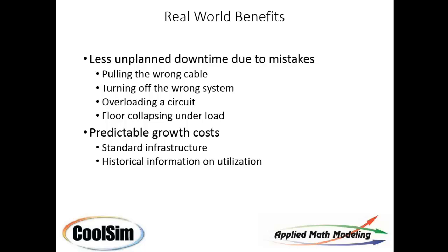As we went to 45U racks and we really started loading those things in with lots of hard drives and got a really heavy load on it, we had a corner of a tile break, basically, and it tilted the cabinet, and we had to get riggers to come in and help move the thing off because we had exceeded what the load was for a tile that was put in back in the 70s. I mean, if you look at the progression over time as to what your loads would be, back then it was pretty common to say, okay, I'm never going to go over 1,000 pounds.